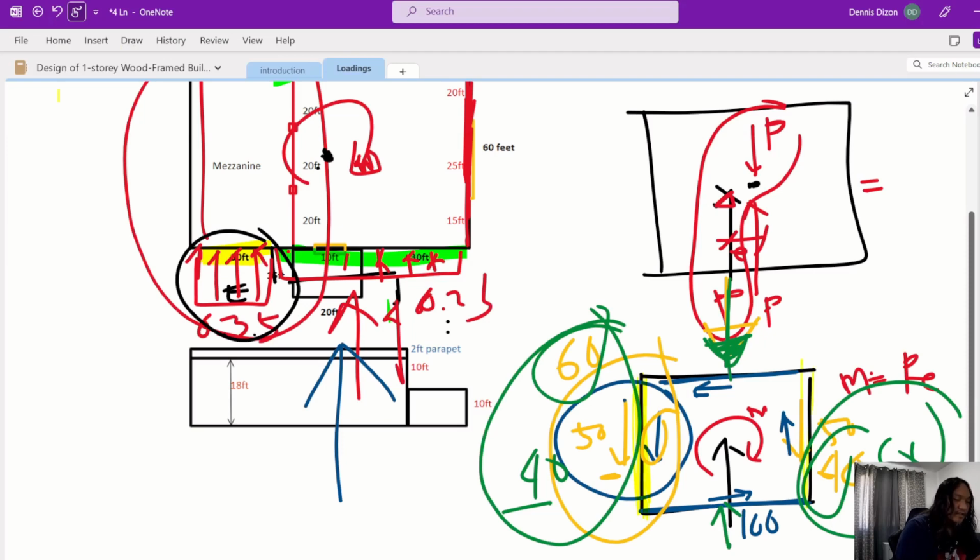So when you design this wall, instead of just using the 50, because the horizontal load is 100, you have to consider the eccentricity. That's why you will design the load by, instead of 50, using the 60 kilonewton load instead of 50. So you have to make sure that you consider that one.